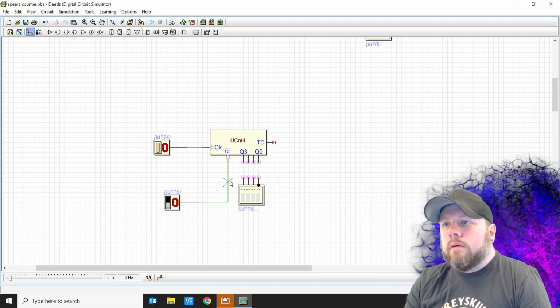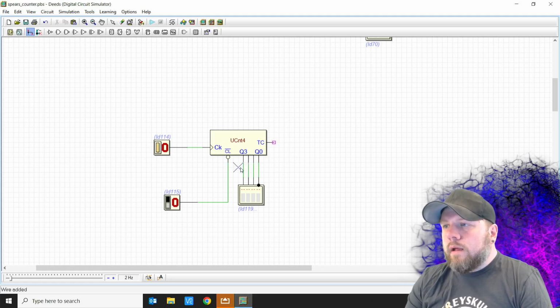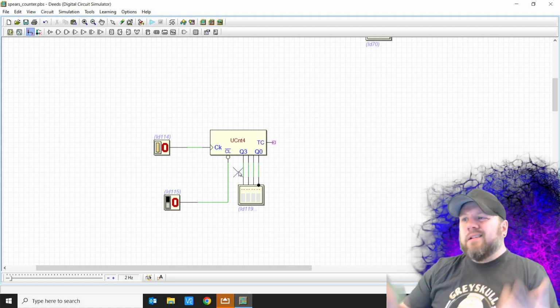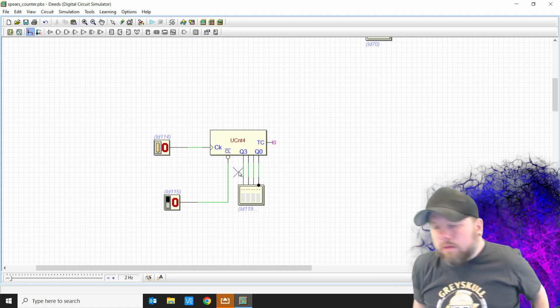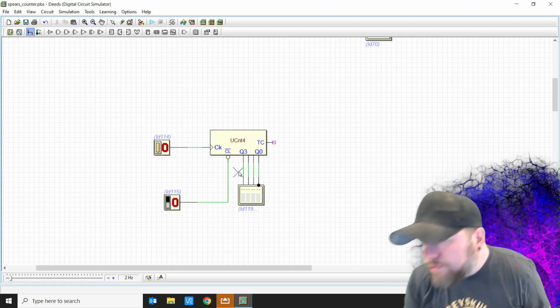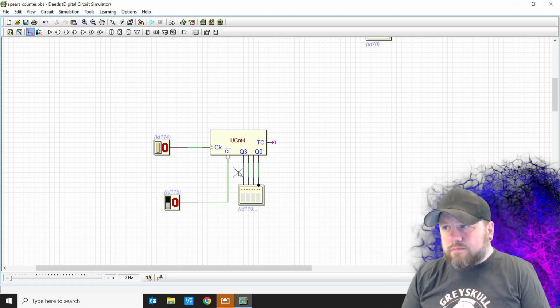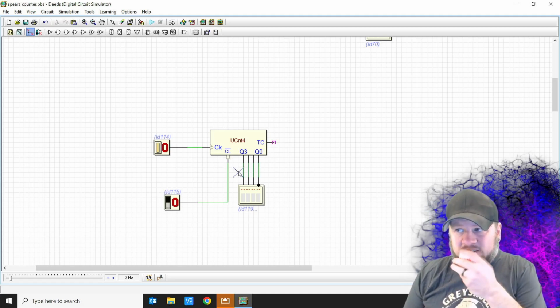A lot of people say, okay, well, I know how a counter works. Well, do they? Or, if we ever, post-apocalyptic world and they're giving tests on how to rebuild society, that box ain't going to do a lot. Like, you can build an AND with switches. You got switches in series. The light bulb's not going to turn on until all of them are turned on. You build an OR gate with switches. Flip any switch. If it's in parallel, the light bulb's going to come on.